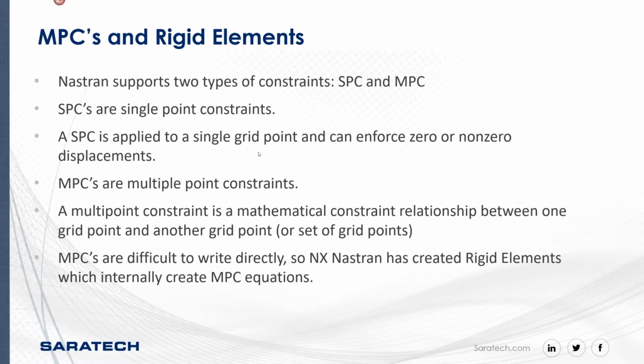MPCs are called multi-point constraints. A multi-point constraint is a mathematical constraint relationship between one grid point and another grid point, or a set of grid points. MPCs are difficult to write. So NASTRAN, or SimCenter NASTRAN, now created these element types called rigid elements, which internally create MPC equations.